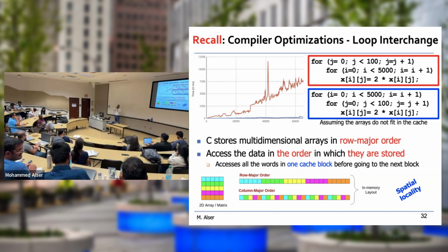So the first part of the column exists in a row. So you're going to access that row, pre-charge, finish from the row. Now you move to the next row, you want to access only the first part of it because you are accessing the entire column now. You access another row, you bring only the first part of it, you access another row, and so on.